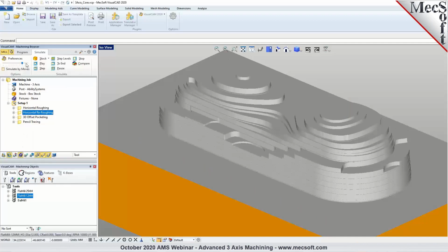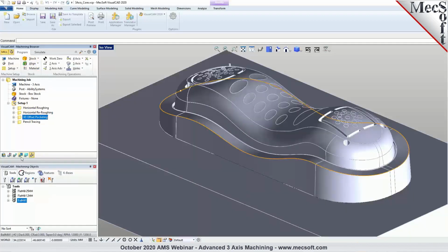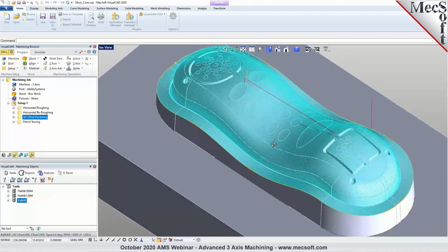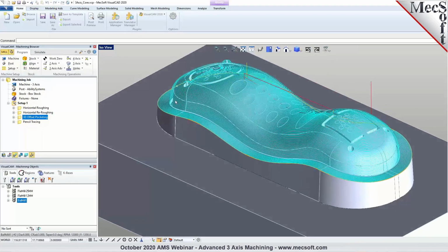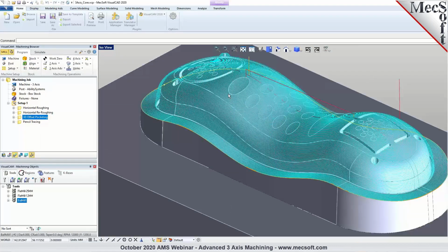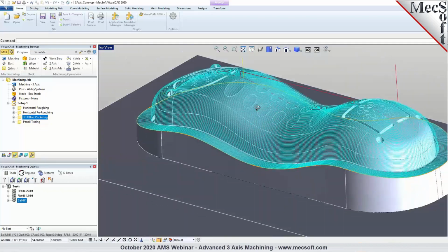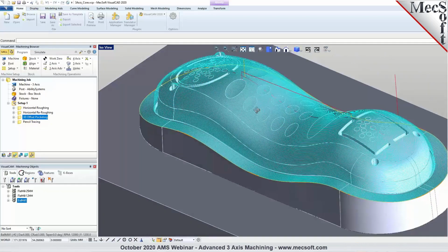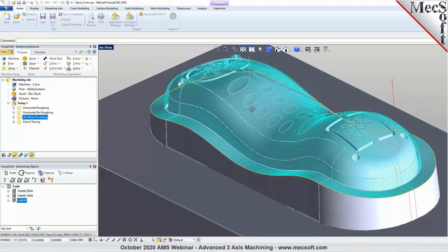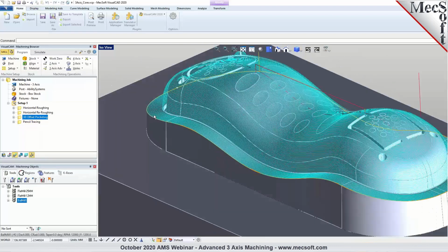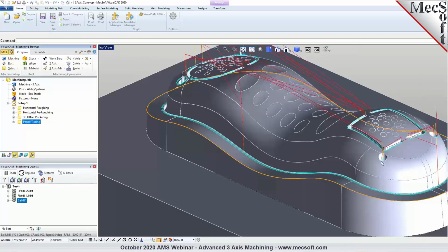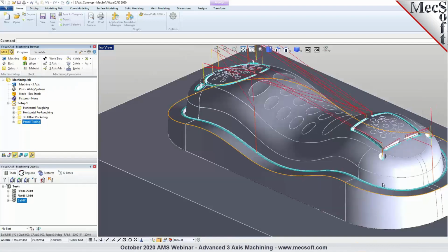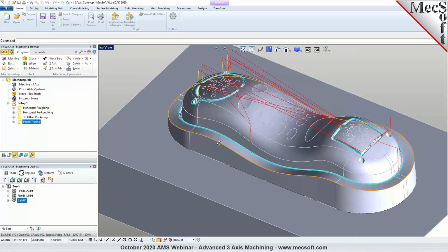And then you have your finishing toolpaths, which could be a 3D offset pocketing, which creates a constant 3D step over or uniform step over. So this can be used for both mold cores and cavities, the 3D offset pocketing method. And you could apply a cleanup pass to go back and identify those bitangencies to clean it up using a pencil tracing toolpath to clean those areas out.